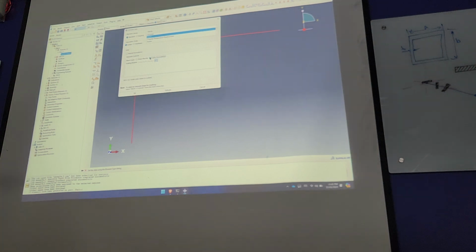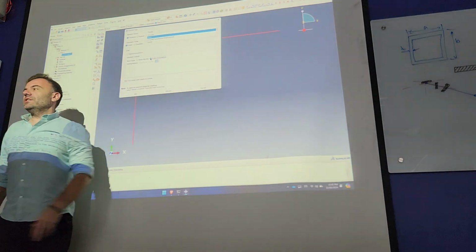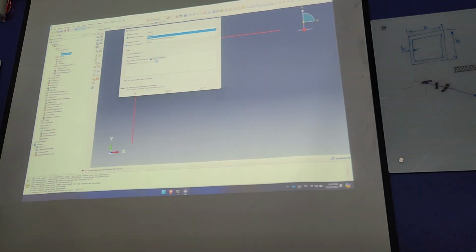So I see there are good options. It says shear flexible, cubic formulation. Which one is which? The default option. That's theory that you need to go and revise. Yeah? So shear flexible is Timoshenko, cubic formulation is Bernoulli.